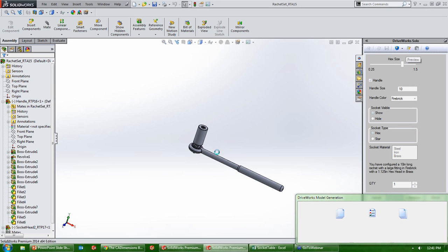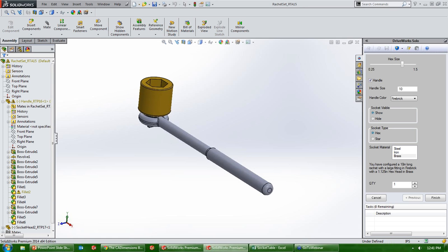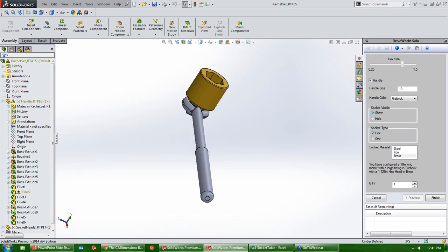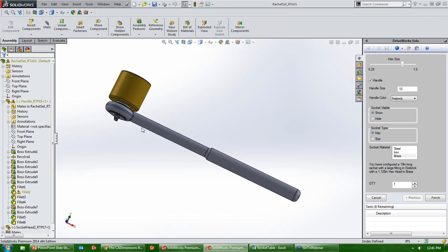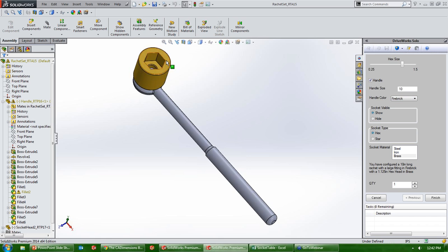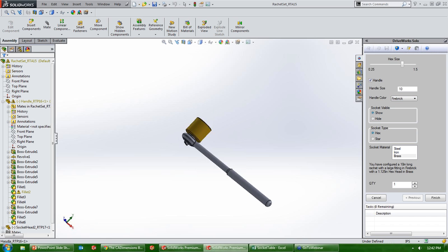and we're going to let SolidWorks build this model using the inputs from DriveWorks. So you'll see we got so close. Even though my handle color is called out for fire brick, it's clearly not changing that. So I missed a rule in here. My socket head looks good though. I was able to get a hex head with the correct mating, and I don't have any errors.